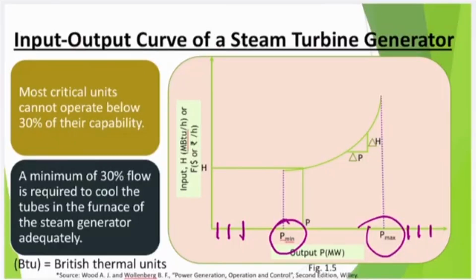If I say that my machine is rated at 100 kVA and my reactive power generated is 10 kVAr, then from those two, volt ampere and kVAr, I can calculate my kilowatt, and hence the P generated cannot be 100 watt for a 100 volt ampere machine, because there must be some reactive power at all given points of time.